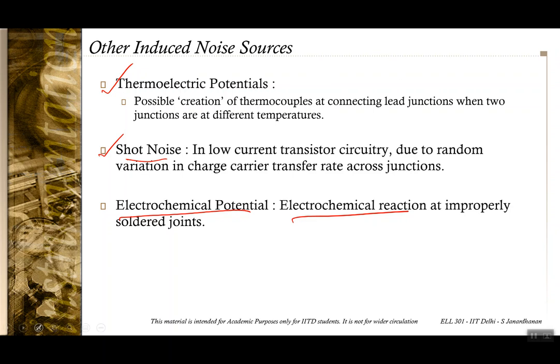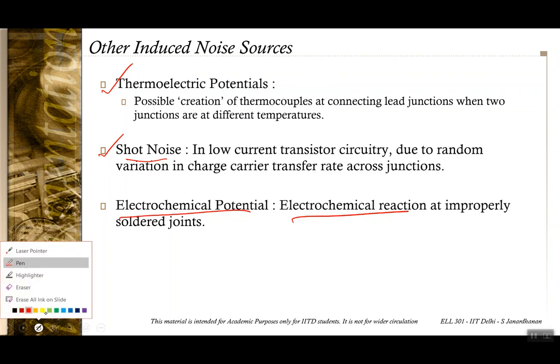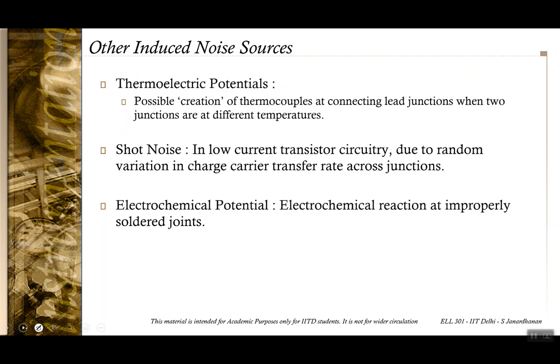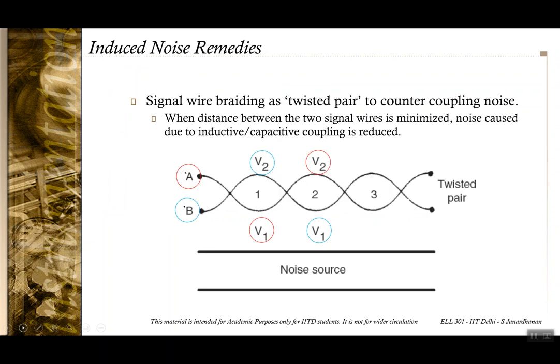And like the remedy for other types of noises, you can also remedy induced noise. The simplest way to combat the inductive and capacitive coupling is to braid wires.